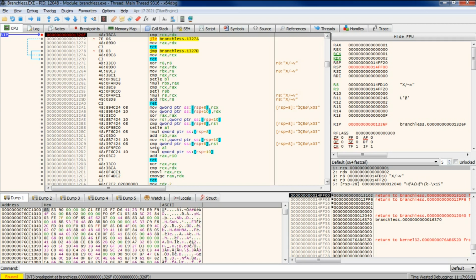So the first thing we do is compare A comma B. Notice here before the comparison, the sign flag is 0. Sign represents a negative. So this comparison is going to take 1 minus 2, which results in a negative number, and the sign flag will turn high. So let's do that.